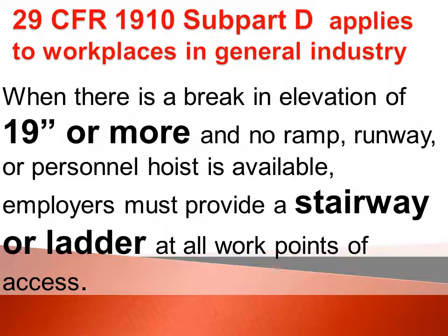Where there is a break in elevation of 19 inches or more and no ramp, runway, or personal hoist is available, the employer must provide a stairway or a ladder at all work points of access.